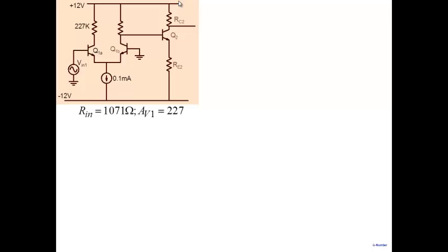And that makes it a little bit more difficult to implement in a lab. So I'll show you the results for this particular op-amp that some students had implemented in the lab, and the performance of that particular op-amp. So anyway, we looked at this differential pair, and we designed it with the aim of satisfying first the input resistance, because it's a multi-stage amplifier. The burden of satisfying the input resistance is on the differential pair. That's the first stage here.